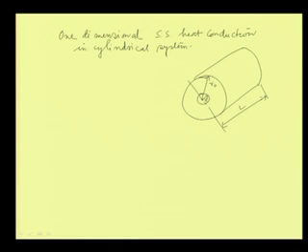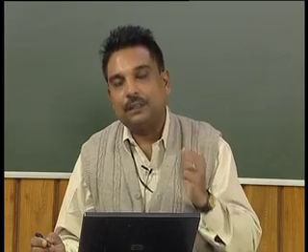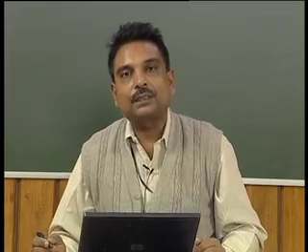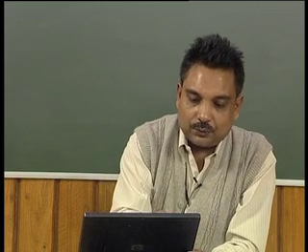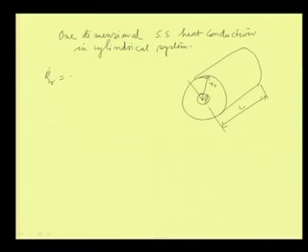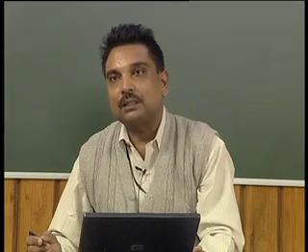Again, if we look at Fourier's first law of heat conduction, the phenomenological law, according to that Q dot R is equal to minus K A dT by dr. I am straightaway writing dT by dr here, because we have already discussed these issues in the case of the plane wall. Now, the temperature is only a function of the r direction. It is not a function of time, because we are considering the steady state situation, and it is not a function of theta and z coordinates in the cylindrical system.